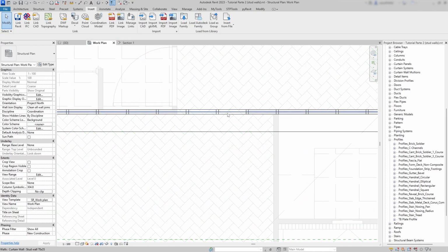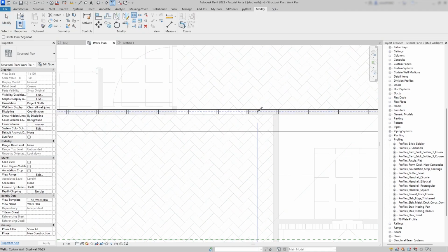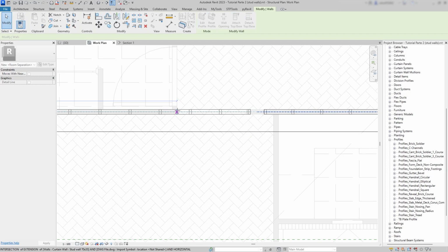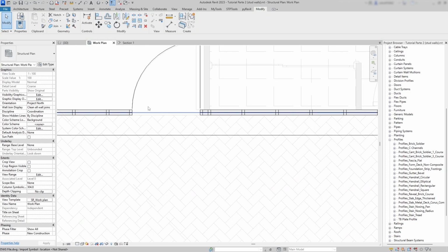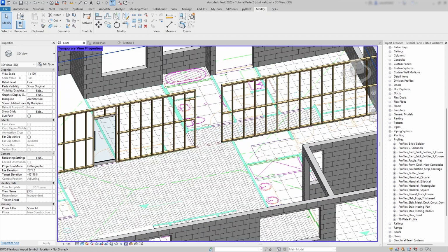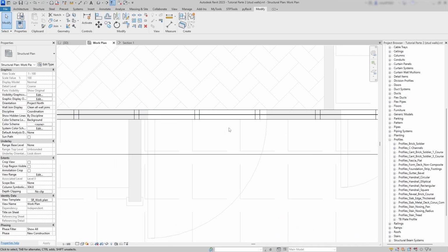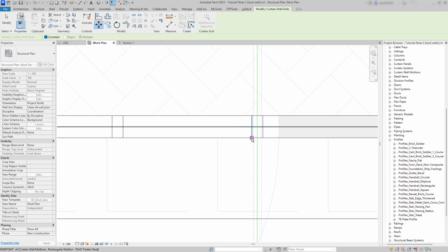If needed, you can also use the split tool to separate the wall into sections in case you don't actually need a physical door. Just split the wall, adjust both sides, and the wall usually adapts automatically while keeping most of the configuration we already modified. In this case, luckily it didn't mess anything up.